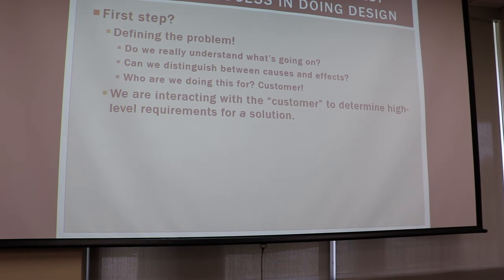So I deal in measurements of 1/1000th of an inch, and I talk about thousandths, and I've had people come in and be like, wait a minute, tenths, hundredths, what? What's 1/1000th? What are we talking about? Because they didn't understand what it is that I'm trying to do. I say a tenth. A tenth is a tenth of 1/1000th, so it's 10/1000ths. It's a very, very small measurement. But if we're not speaking the same language, then we're not going to get what it is that we want.